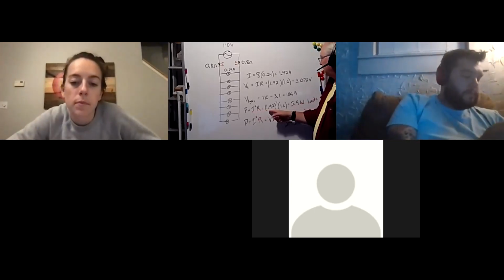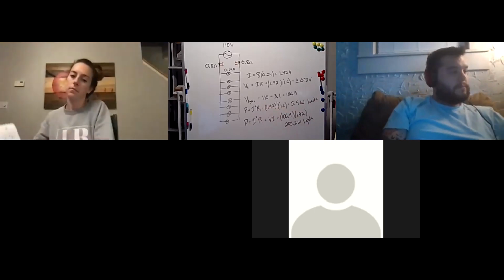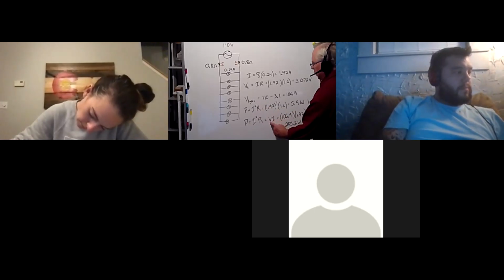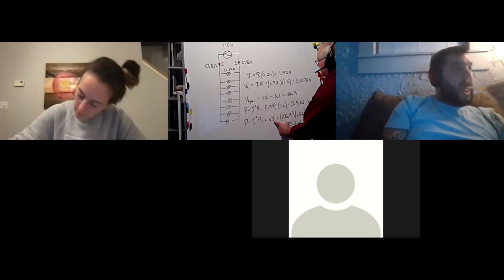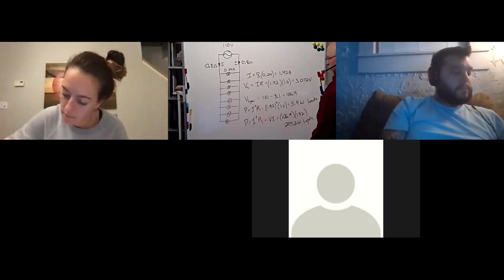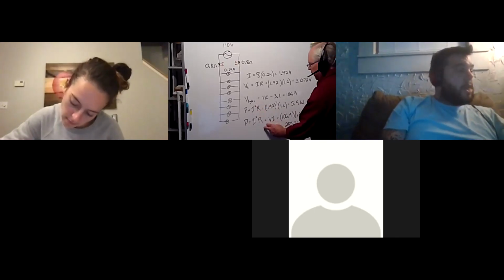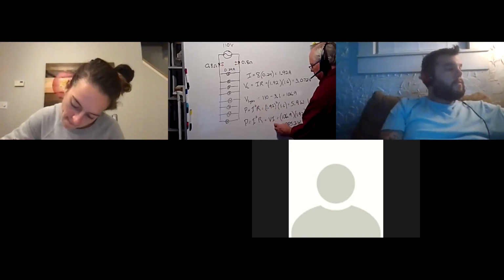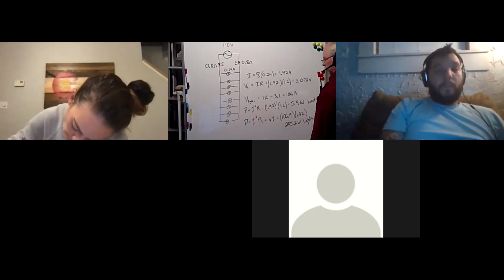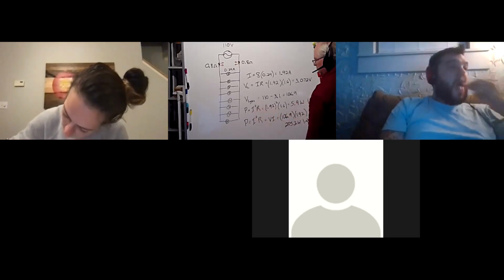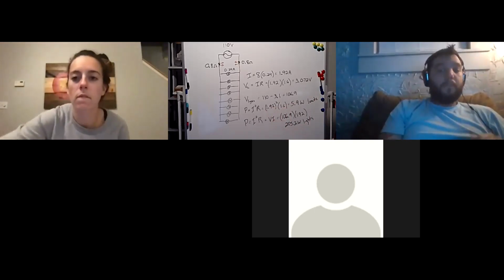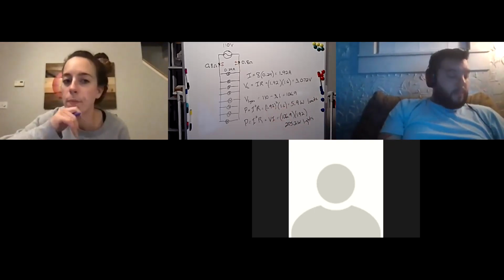So the rate at which the power lines lose heat is I squared R. So you can transmit the same amount of power by having a very large V and a small I. And that benefits you because I squared R is the amount that you're losing in the transmission lines. So that's how come energy is transmitted at high voltage and low current. It's because it cuts down on the power loss. Even at that, the current is going to be several hundred amps, and so those power lines need to be really thick pipes.